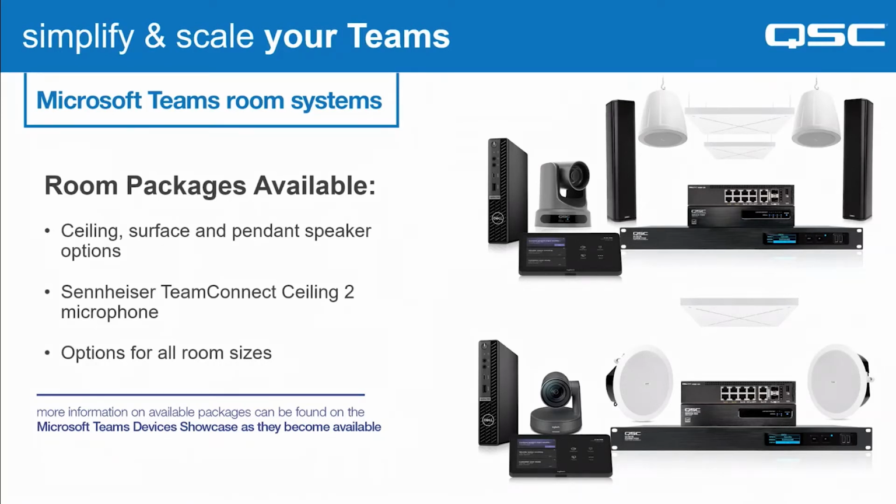With Qsys, we've still got that one connection to the Teams PC, but we could have 2 cameras, 3 cameras, 4 cameras, whatever you want, and we can switch between all of those. And we're not actually switching on the USB end, we're switching on the network end. So the Teams PC is not doing anything clever, it's just seeing a single webcam, but we can have multiple cameras going into that. And that's why it's going to be really good for larger spaces where you want to have different angles and that sort of thing.